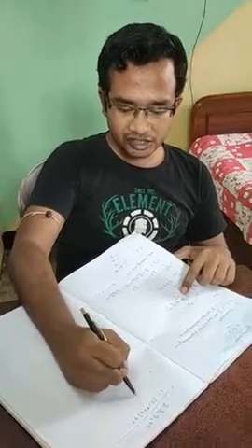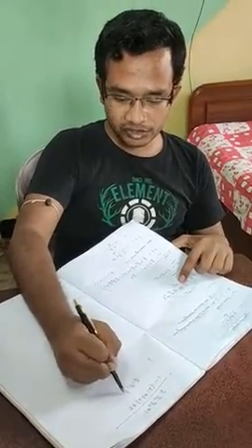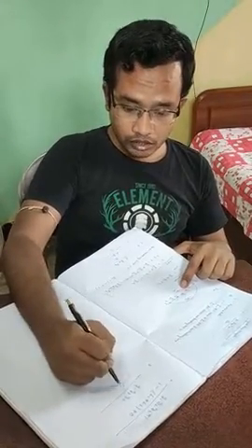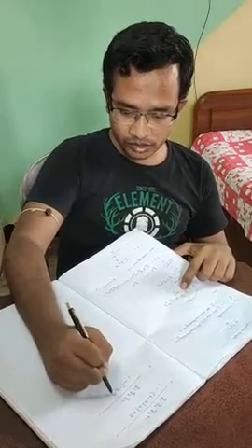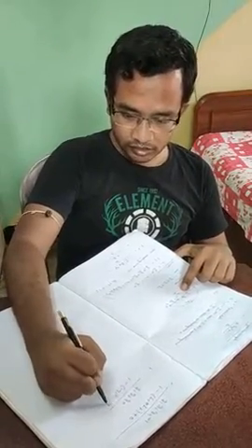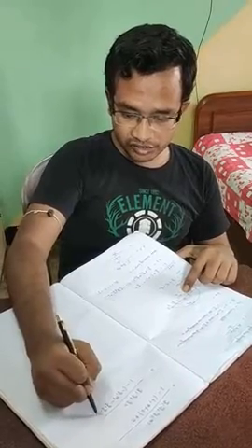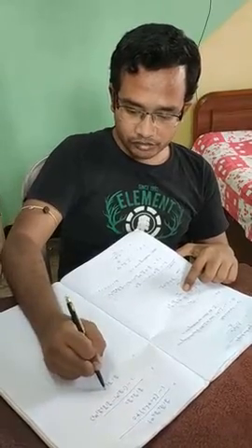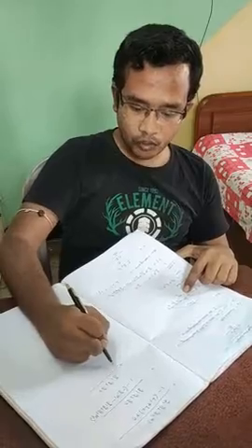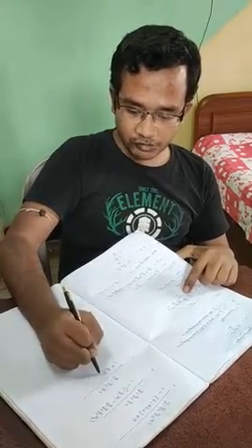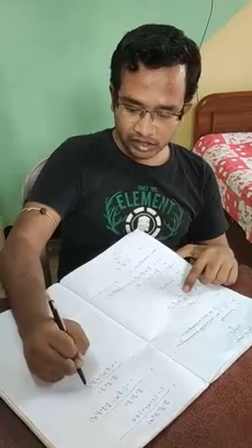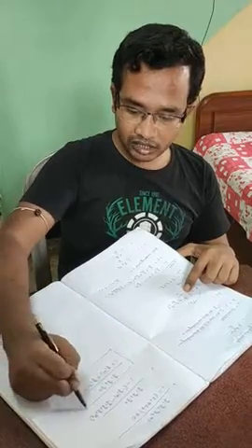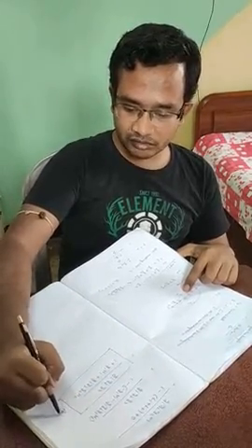So this gives us G1 G2 G3 divided by 1 minus (minus G2 H1 minus G1 G2 G3 H2). Now simplify it: G1 G2 G3 divided by 1 plus G2 H1 plus G1 G2 G3 H2. Now this is the result, the transfer function.